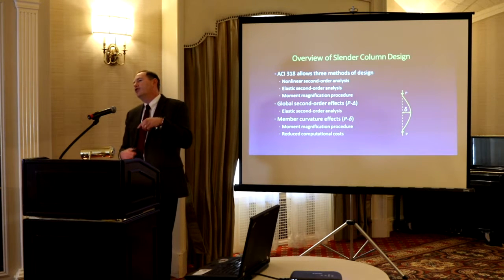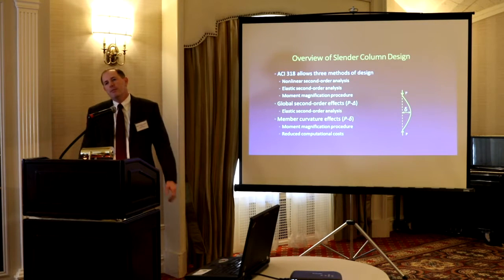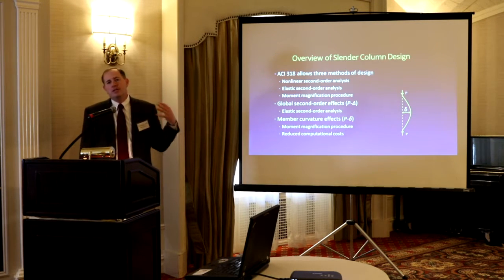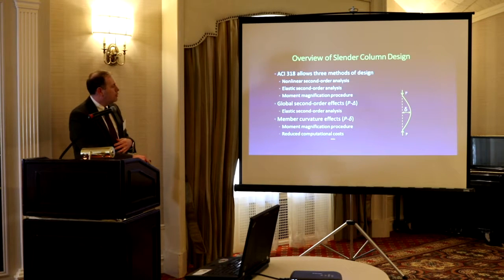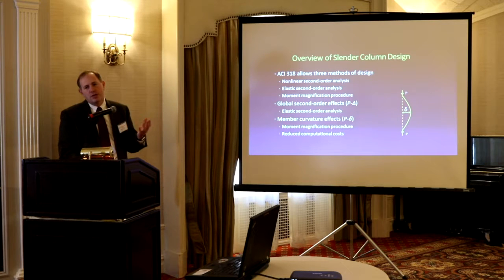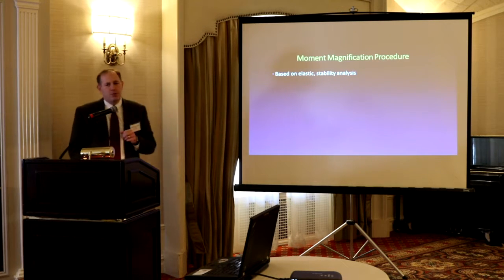Also, the EI recommended by the code to use is a different EI than the overall frame. So the P little delta is really still a hand procedure that needs to be done here. And so this is the way to do it, reducing computational cost, obviously, if you're not having to put nodes everywhere. Let me talk about this procedure.